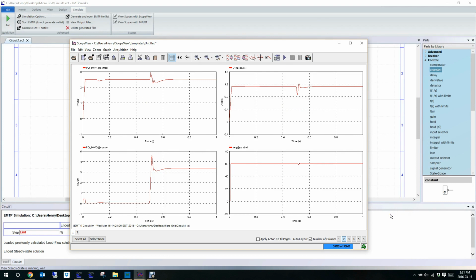Because as soon as we get islanded, we change the mode, and we go from PQ to VF. So the DG is the slack, and it does everything it can. It produces the amount of power necessary to maintain the voltage and the frequency. And so you see that the reactive power generation increases a lot, and the real power remains kind of the